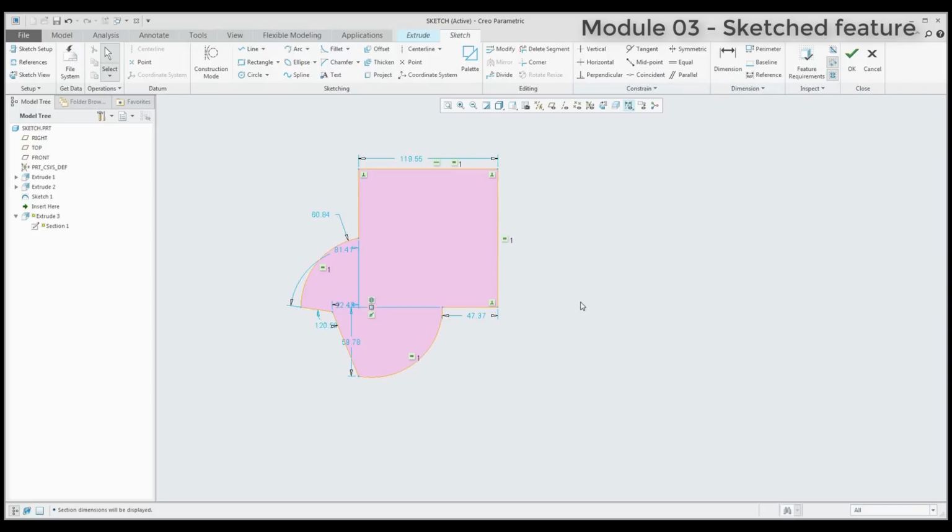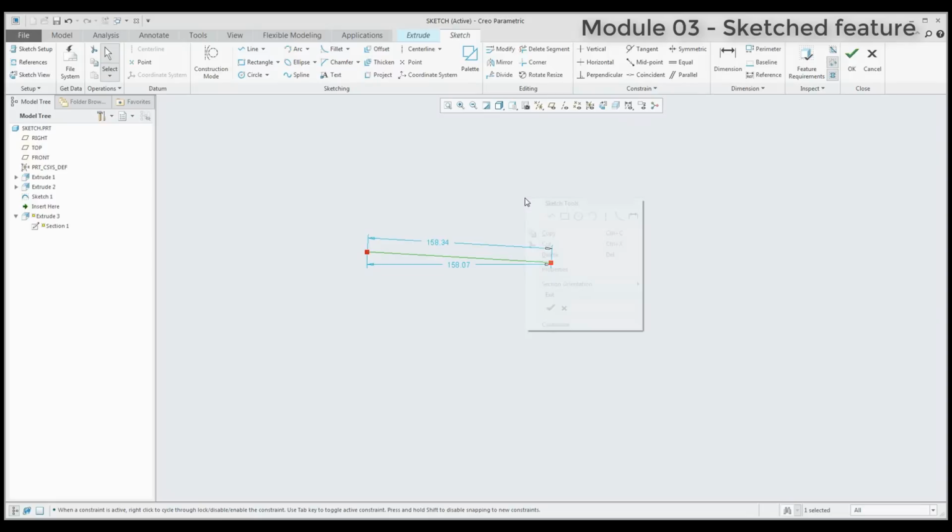So right now I'd like to focus on some dimensions. What does it mean? Okay, we would like to create, for example, a line. This line can be horizontal. And then I would like to create the arc. And if you select the arc and follow the line, the system will automatically create a tangent feature for you. Or if you don't want to use the tangent, you need to go perpendicular. And right now it's not tangent to the selected edge. Yeah, so it's up to you how you work with the combination of the line and arc feature.